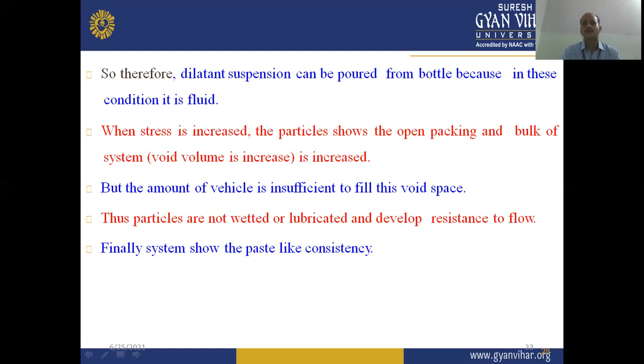Void volume is also increased. But the amount of vehicle is insufficient to fill this void space. So these particles are not wetted or lubricated and develop resistance to flow. Finally, the system shows a paste-like consistency, which is known as dilatancy.